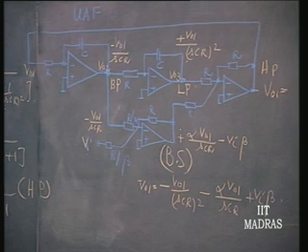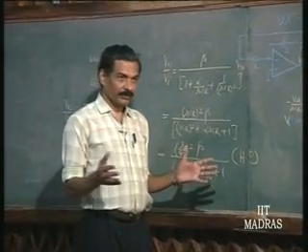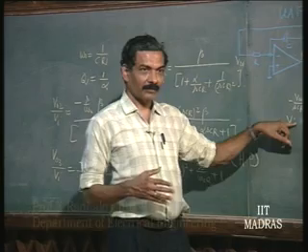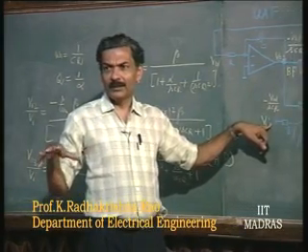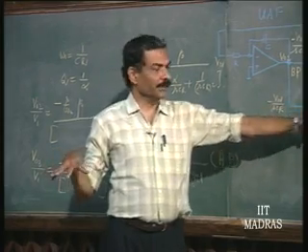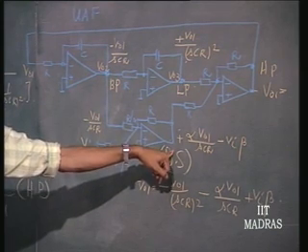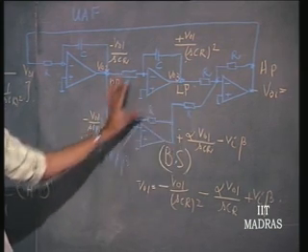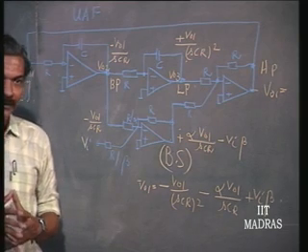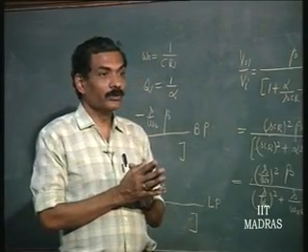So, that is why this circuit is very important, because we can just use it for even biomedical application where you want an ECG waveform, which is coming here, which contains a lot of your so called 50 hertz. Output of this is going to be the same ECG waveform, devoid of the 50 hertz. So, this is a nice setup for that kind of filtering in biomedical applications. So, let us now see how this can be converted into a voltage controlled filter.